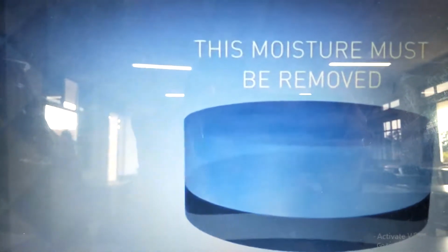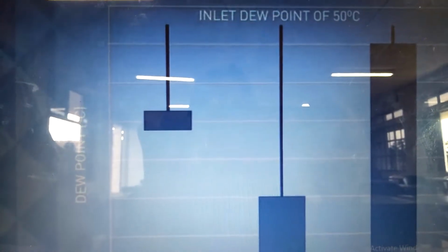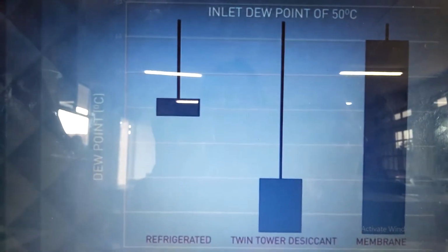to ensure trouble-free operation. Unlike traditional desiccant or refrigerant dryer systems that produce a fixed outlet dew point, Pentair's advanced membrane modules are designed to reduce the incoming air moisture concentration. Dew point suppression can be optimized based on required air quality.